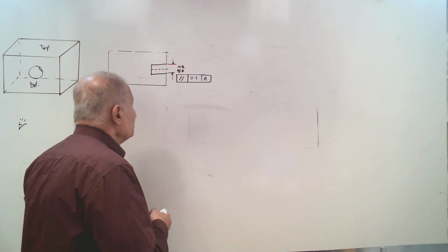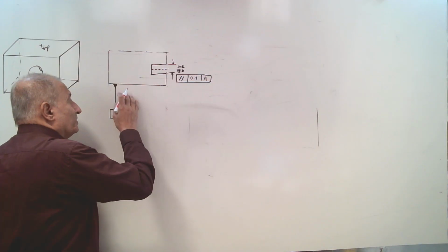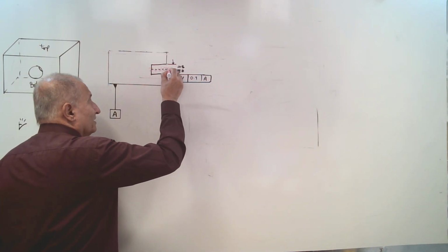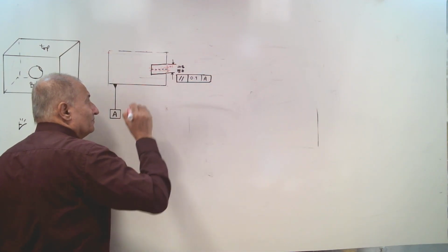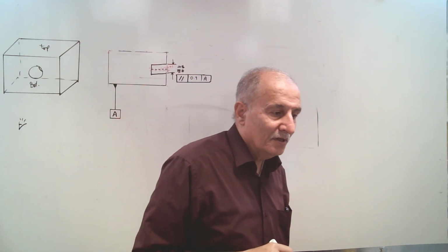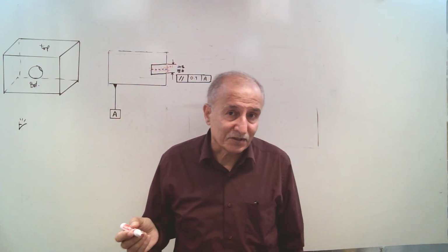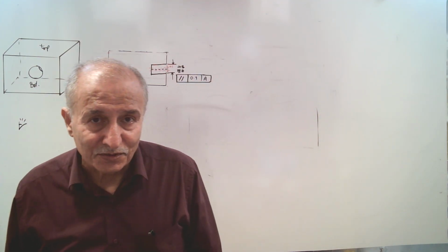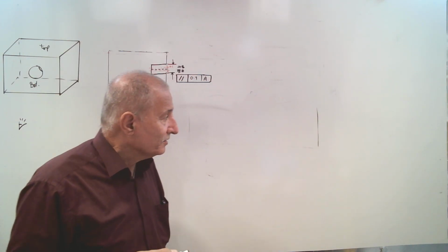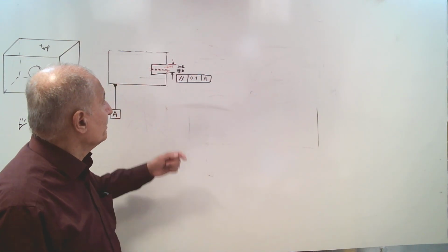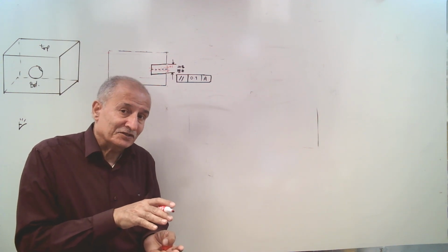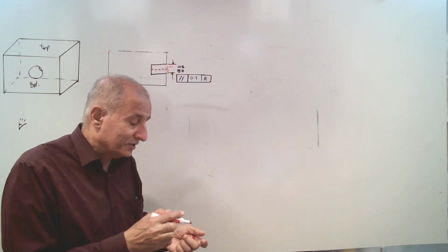Then the zone shape must be parallel. It means two parallel planes. They are 0.1 mm apart. That's the size of the tolerance zone. We call it zone size. Then the zone shape here is the space between two parallel planes that contain the center plane or set of points.